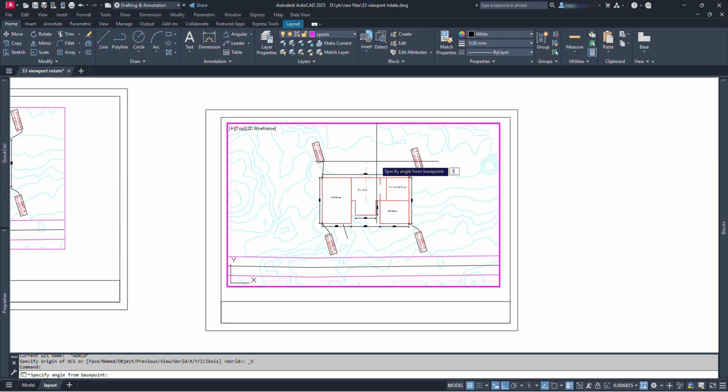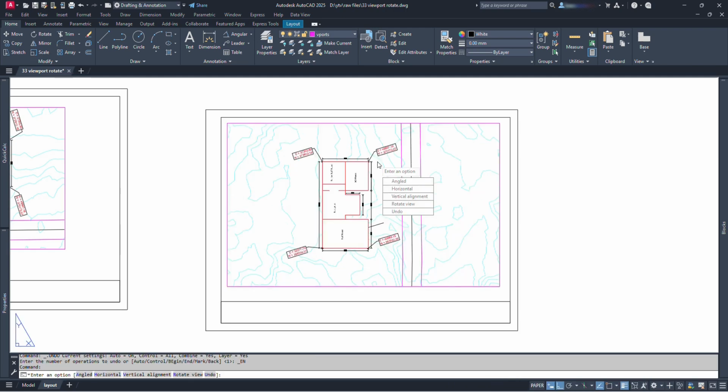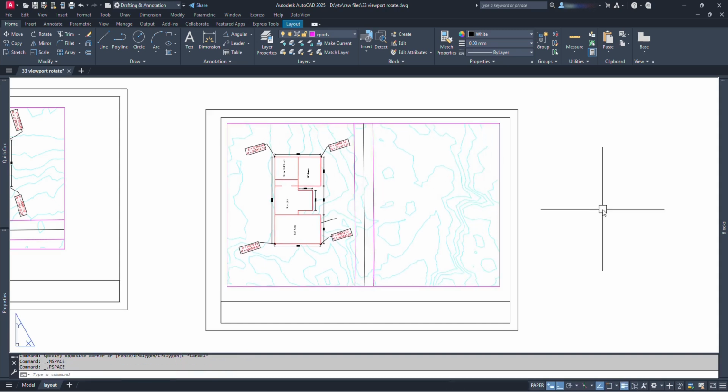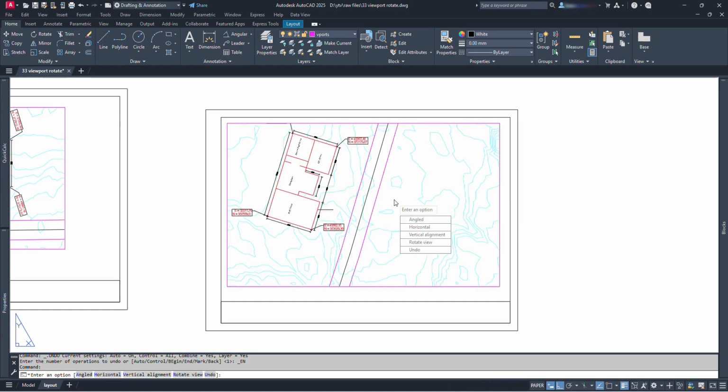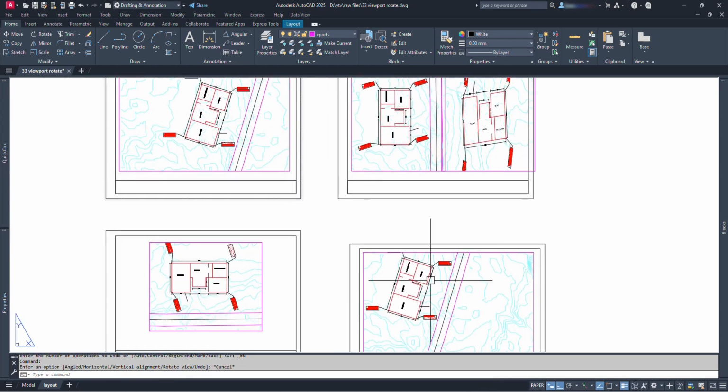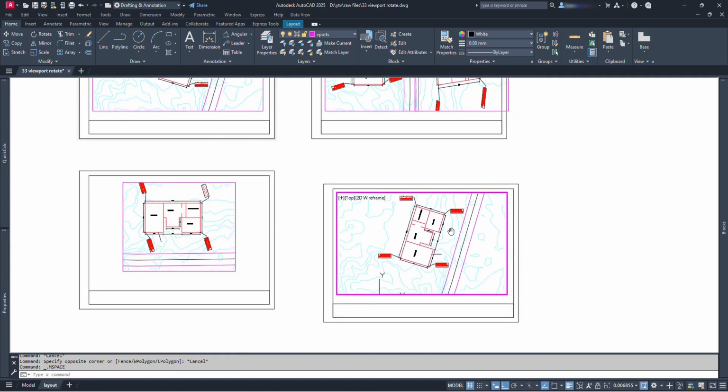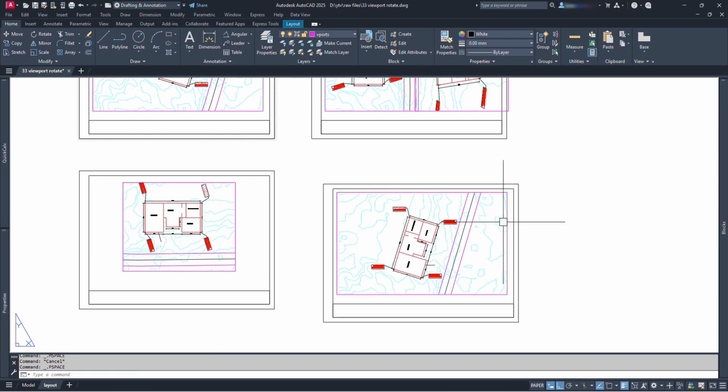So, let's type 17 and press enter. We can see we have rotated the plan to vertical direction. And whenever we want the view back to normal, we can rotate the view by 0 degree using the MVSETUP and the view comes to a normal or original view. So, in this method also we don't have problem with changing of coordinate system. So this could also be better than the first option we have tried.